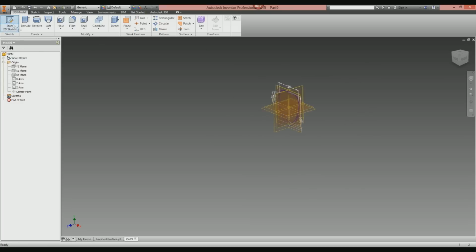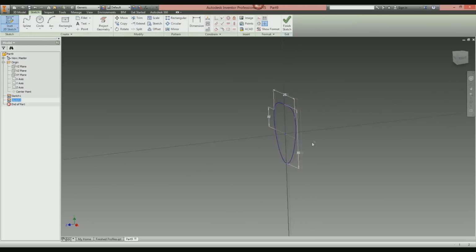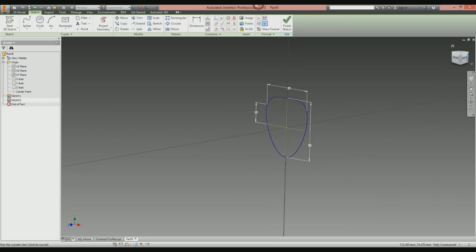Right, well I'm going to create a sketch. And I'm going to sketch on this plane here, which is, because I've made everything symmetrical around that center point, this plane here runs smack bang through the center of the sketch. It is effectively a center line. If I just turn around, you can see there I'm sketching on this plane here, which is central through that sketch. Okay, I want to create a center line.